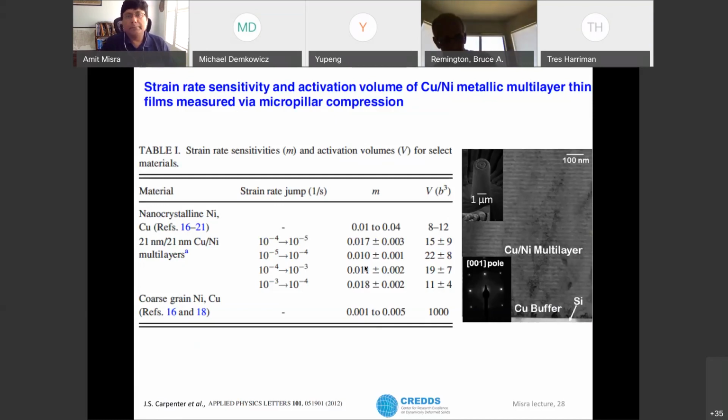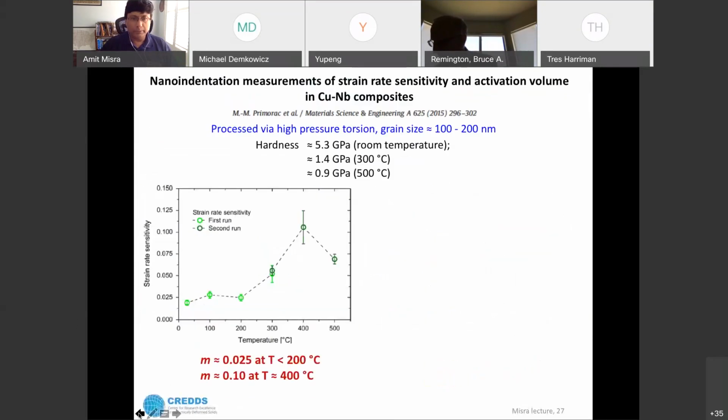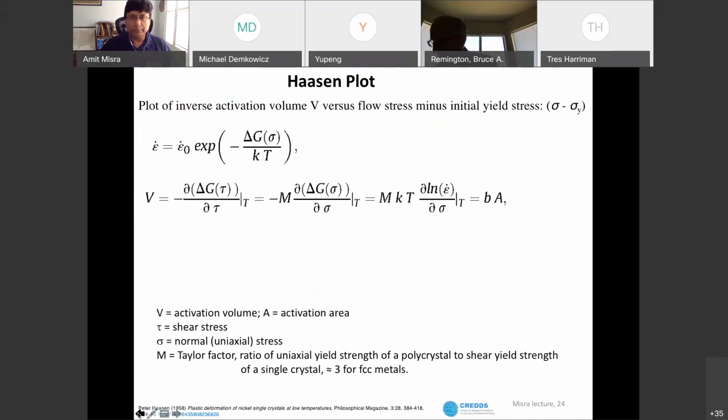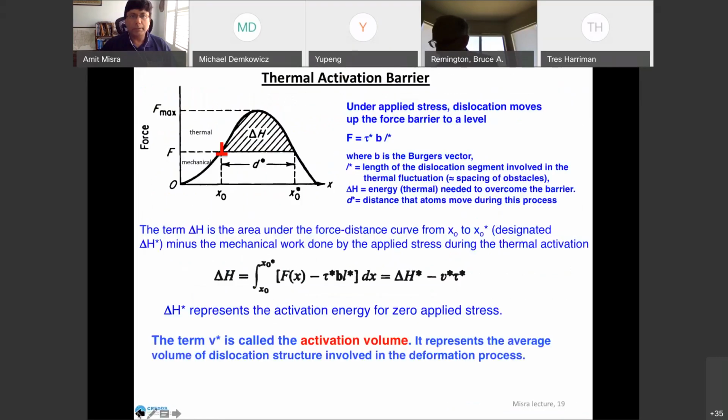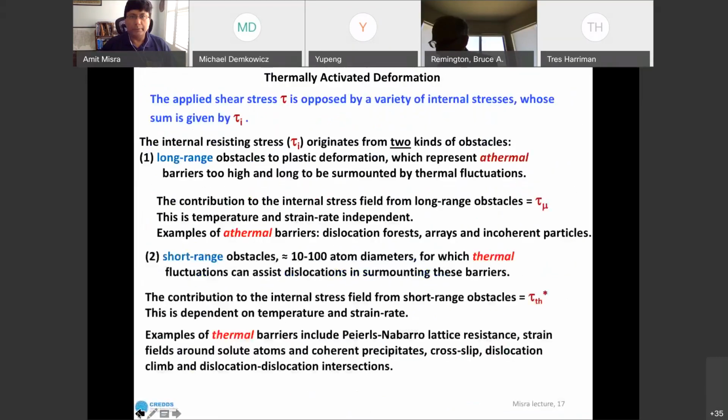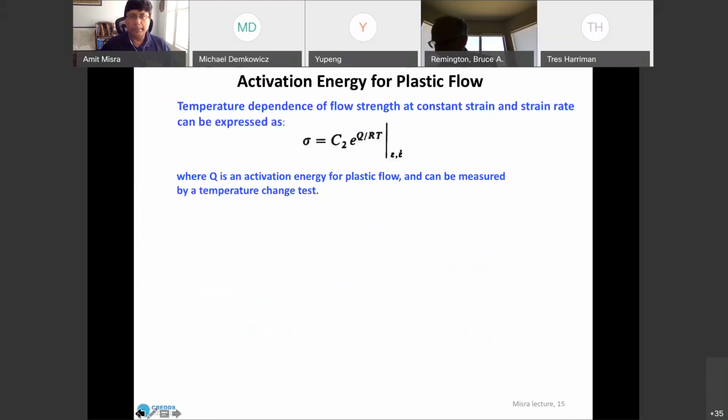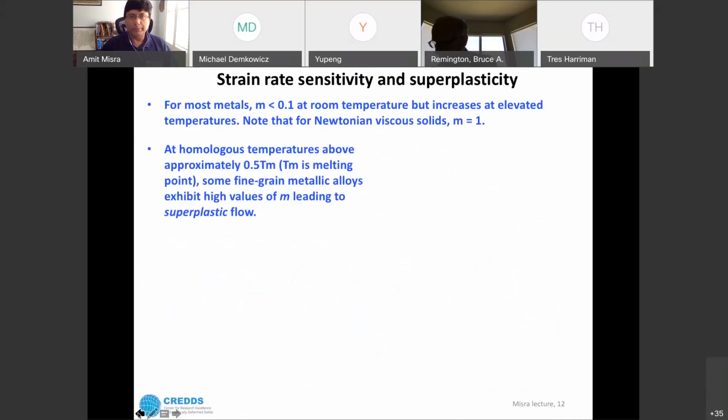Okay, so for this case, may I say this is almost a rate-independent plastic material? It's weakly dependent. Certainly for FCC metals, it's weakly dependent. For BCC metals, it is more highly dependent. In the early slides, I had some flow stress data as a function of strain rate. If you go back, you could see that in some materials, depending on where we are in terms of temperature and strain rate range, you might get a stronger dependence versus a weaker dependence.